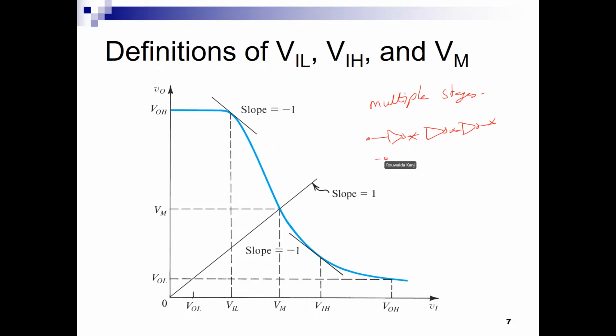If the gain is -0.5, then -0.5 and -0.5, what does the effective gain on the noise come out to at this point? -0.5 to the power 3 is a decimal less than 1, so it's really dropping. But if I have -1.5 to the power 3, it will grow. So it will accumulate. Chances are the noise will continue to amplify as I move through the stages.